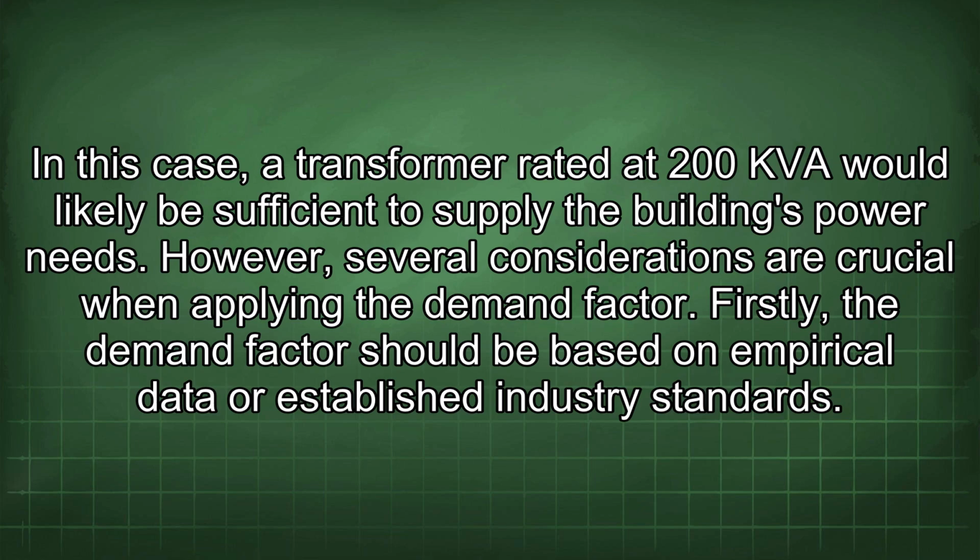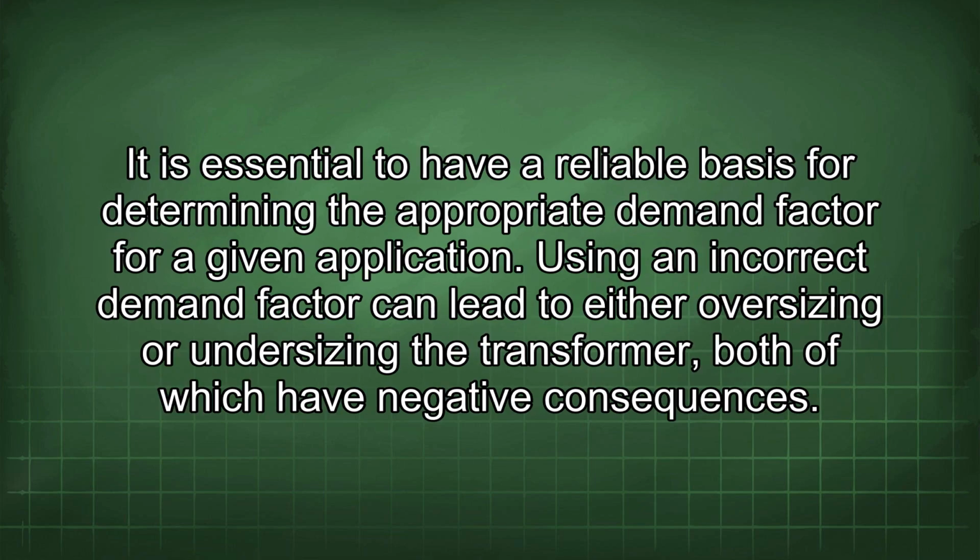However, several considerations are crucial when applying the demand factor. Firstly, the demand factor should be based on empirical data or established industry standards. It is essential to have a reliable basis for determining the appropriate demand factor for a given application. Using an incorrect demand factor can lead to either oversizing or undersizing the transformer, both of which have negative consequences.